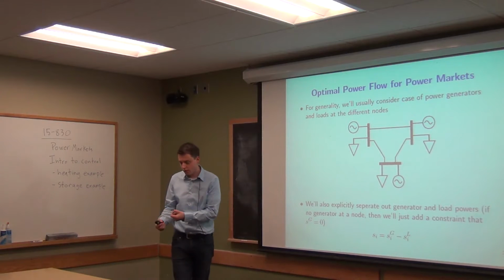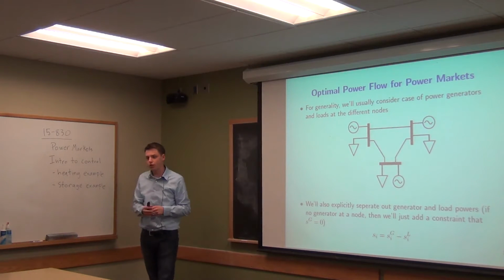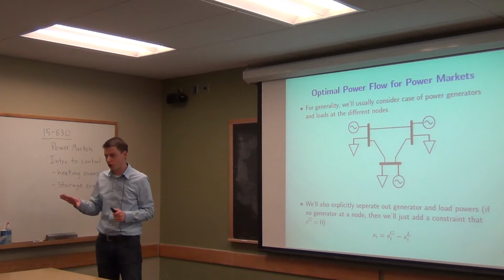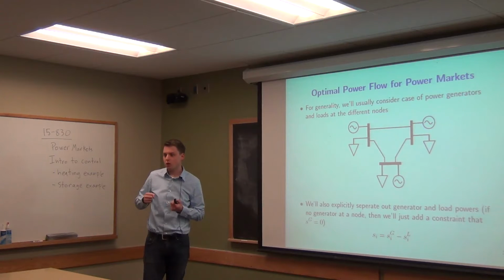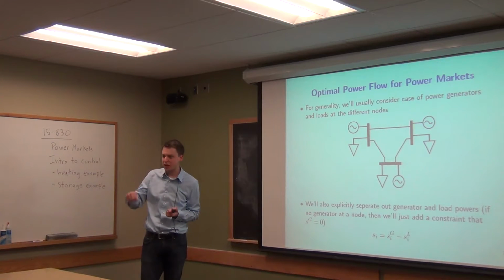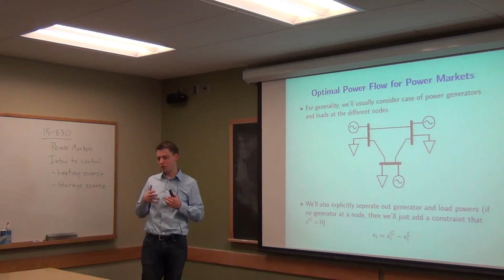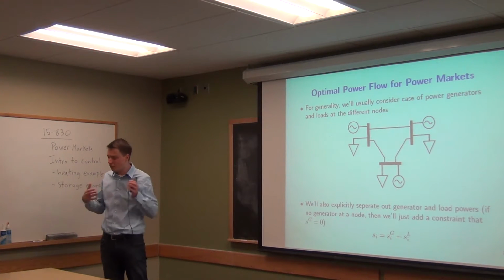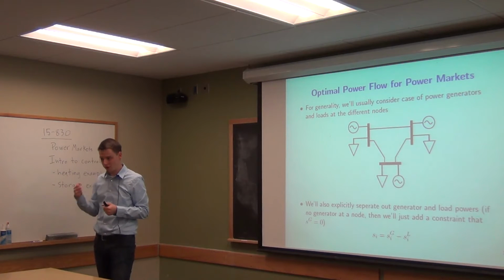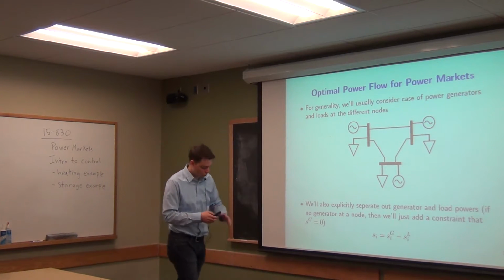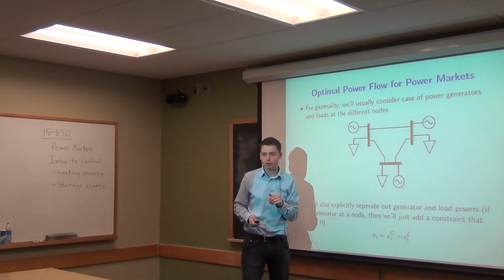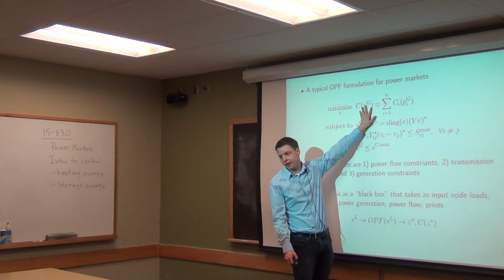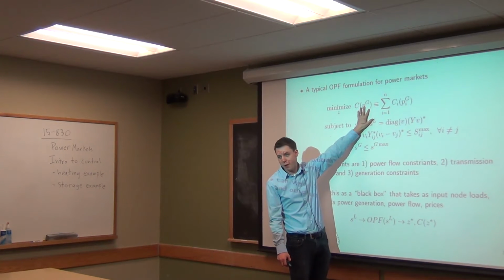respectively. And in general, though there is some cost in some sense to generating reactive power, we typically only put a cost on real power, because that's really what you have to actually generate at the generator itself, right? If you want to produce power, you have to use some amount of fuel, for example. That fuel will produce a force on the turbine, and that will create the real power. So this is really what we think of as having a cost is the real power. So we want to minimize the cost of all generators in typical power markets.